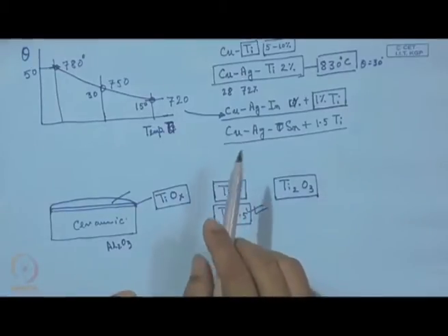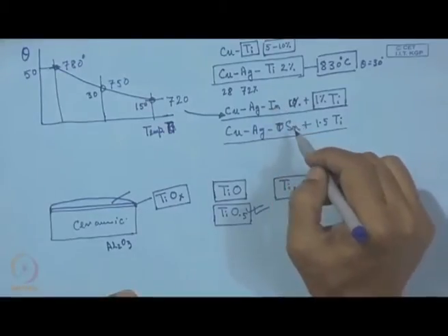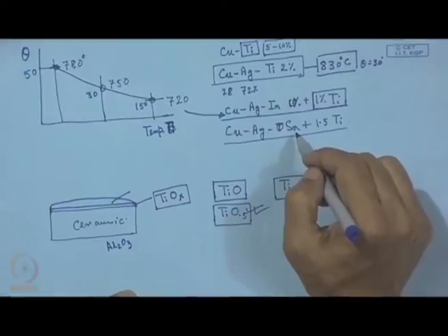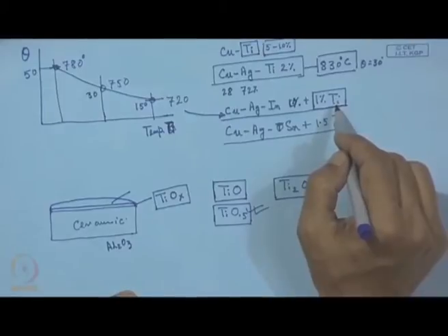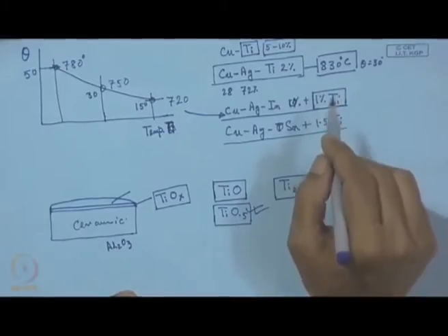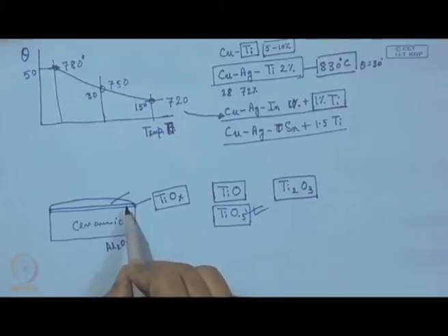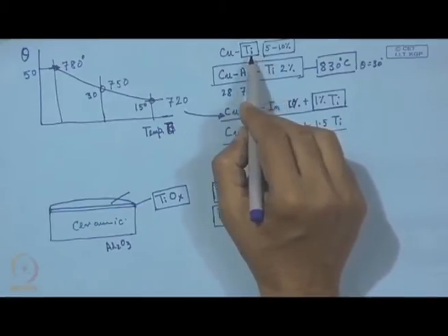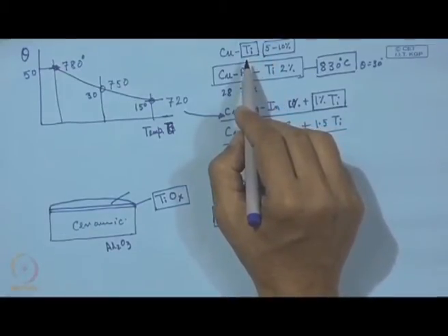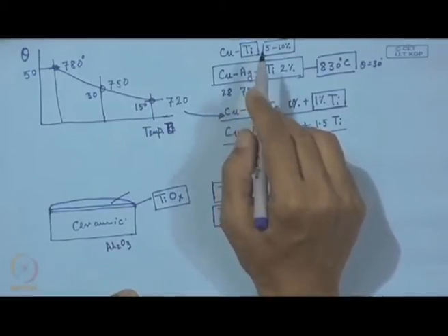So, what we understand is that the presence of indium or tin increases the activity of titanium, and with this small amount of titanium a thin reaction layer is formed readily, which promotes the wetting. But when we have a higher percentage of titanium, this is just not our desire, but this is a necessity without which wetting is not possible.